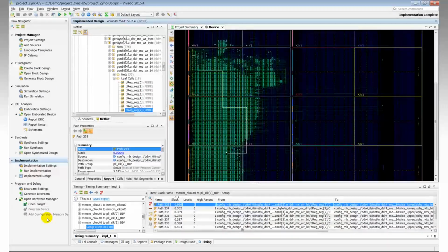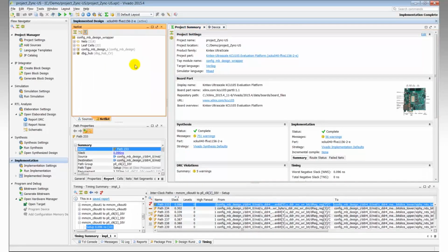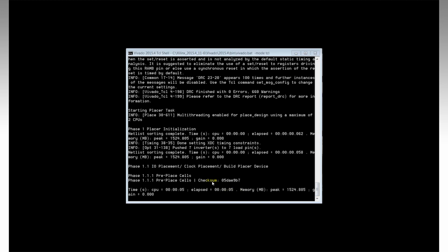So hopefully you can see how tightly integrated all of the features and functionality of the Vivado Design Suite is within the Vivado IDE, which works very, very well in conjunction with the Vivado project. Now, when using projects, a directory structure is created on disk to store the various configurations and optionally the IP, block designs, and sources, as well as results for the design project. As mentioned earlier, most of the features within the Vivado IDE can also be used in non-project mode.